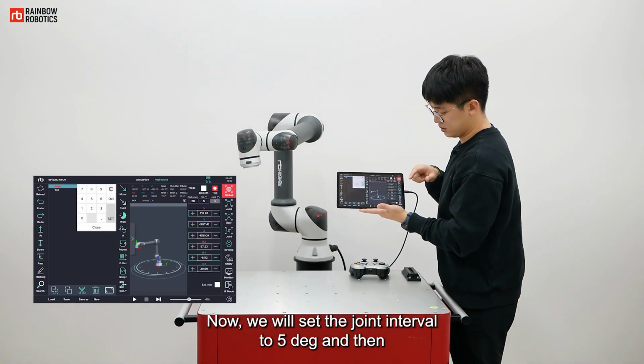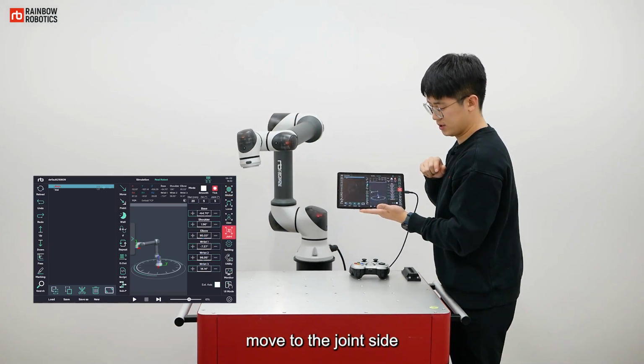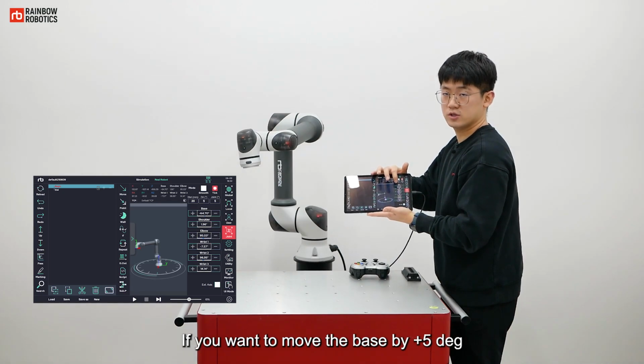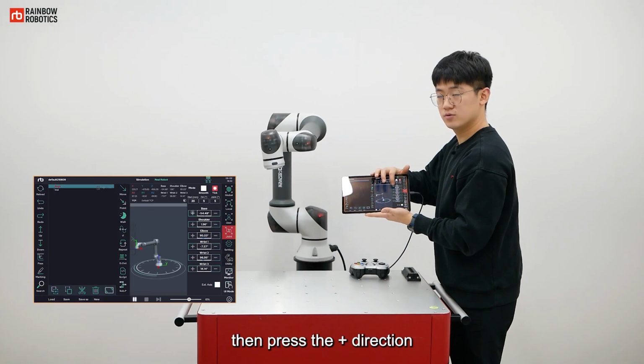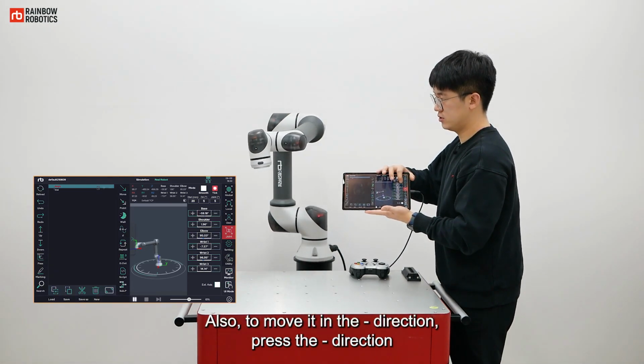Now, we will set the joint interval to 5 degrees and then move to the joint side. If you want to move the base by plus 5 degrees, then press the plus direction. Also, to move it in the minus direction, press the minus direction.